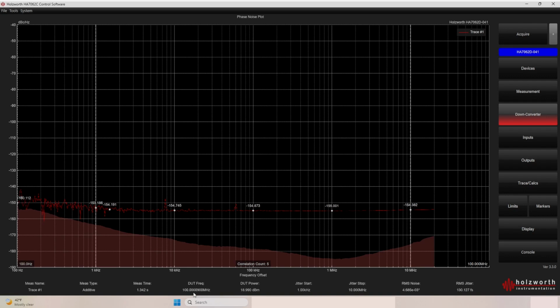Just confirm that your DUT input's correct, that it's working with your electronic phase shifters, along with the specified range for your device under test. And then our DUT power. I don't want to exceed 20 dBm. Currently I'm on the top end of this because I'm splitting the power between our 2 LO channels along with the DUT input. It's registering pretty high.